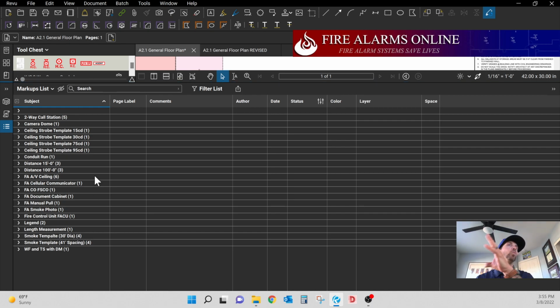You can have this open on one screen and have your Excel sheet or whatever your estimating software is open on another screen. And you could just take your quantities directly off of this and feel with confidence that this is capturing every single device across all 5 pages or whatever it may be of your entire markup. This is not a per page thing. This is the exact quantities of everything you have for your whole markup. So this is where you're going to go to input your device types and quantities into your estimator or whatever it is you're using to put your bids together.